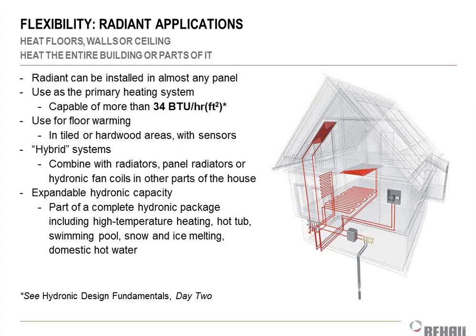You can also use it for floor tempering. So if you want to add some radiant heating in a space, you can do that and temper the floor. This is more common in residential, where people want their kitchen floor, bathroom, powder room, and master bathroom to be tempered so they can walk on it barefoot, whereas the carpeted area they're fine with already. So sometimes we'll do that kind of thing where we temper the floor.